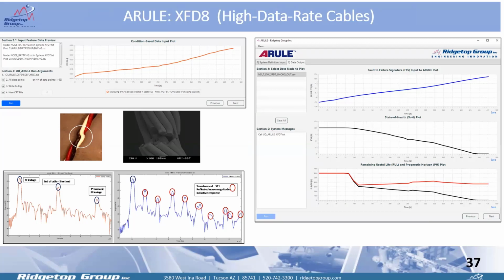We were asked if it was possible to set up a system to detect the damage and prognose when it was going to fail without having to take this antenna off a submarine, because it's hard to measure the cable that's inside the sail of a submarine. What you actually have to do is lift the antenna out with a crane. And you just can't take even a measuring tool to measure resistance. You're not going to detect broken strands.